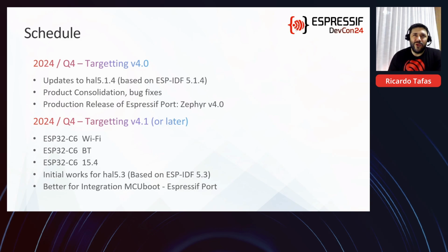We most likely will begin our migration from HAL 5.1 to HAL 5.3. And we do expect a better integration of the Espressif port of MCUboot with Zephyr. Just a small take here. Currently you need to build them separately, and we want to improve that.